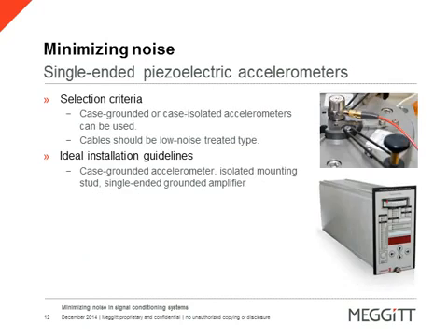And then we reach the single-ended piezoelectric accelerometers. Again, we have case-grounded and case-isolated accelerometers. We provide these for many applications, which is installation and application specific, so we provide those for the customer to choose from. Since this is a piezoelectric accelerometer, low noise cable must be used with these. You cannot use these sensors without it, otherwise you will introduce noise, mainly due to the triboelectric effect.